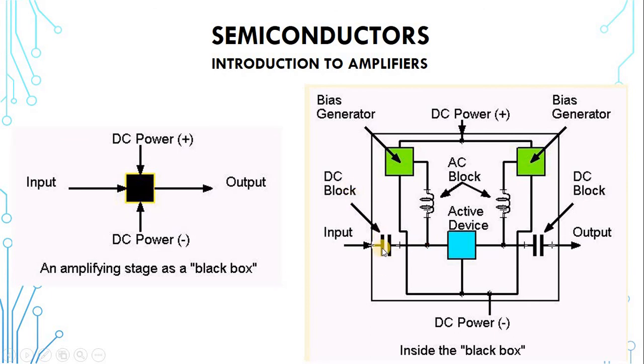So the capacitor here is here to filter out or block any DC component that may be in your audio signal. So at the end of the day, once the DC is blocked, you have only the audio getting here to be amplified. And there's another one at the R2 stage. Just in case the first DC block, the capacitor, does not do a very good job, and some of the DC components end up being amplified together with your audio, then this one will do the final work by blocking them so that your loudspeakers will not have noise in them. You can hear your audio clearly.